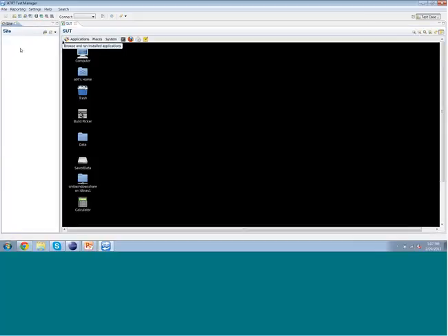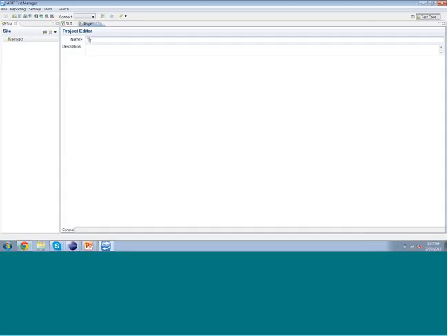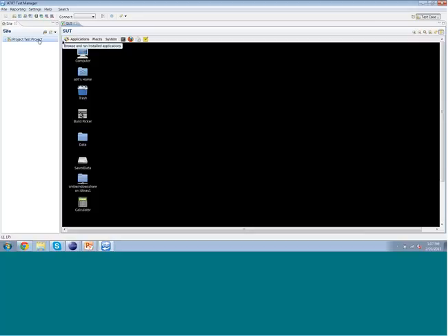On the left-hand side here is the site view. This is our hierarchy, our left-hand list. Basically, this is how you're going to lay out the organization and flow of your test. Underneath the site, at the top level, the first thing we create is a project. This project is where you're going to store pretty much everything for your test. I'm going to open up the editor for that and call this one Test Project. Everything within ATRT is saved on the fly. There's no need to do a file save or anything like that, so if anything happens, your work is saved.